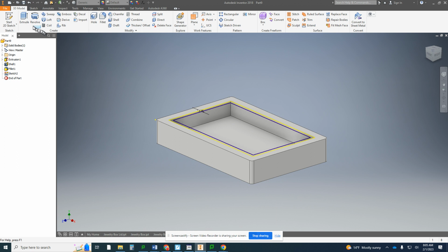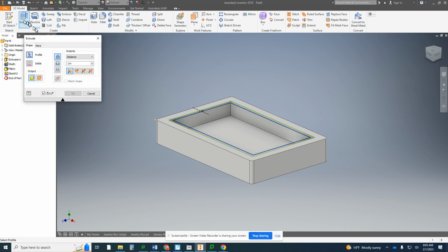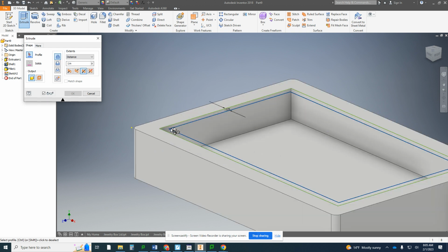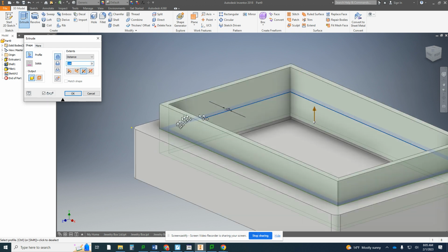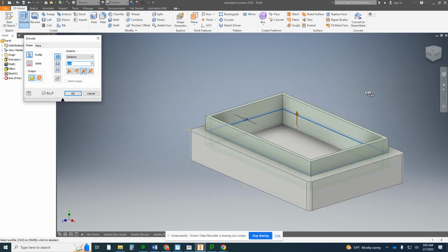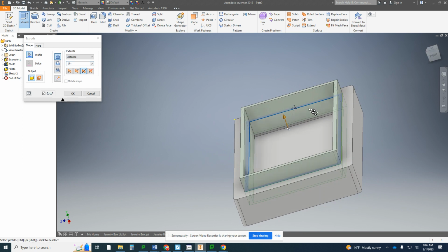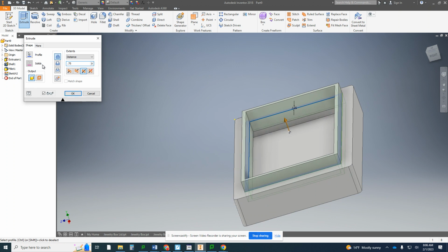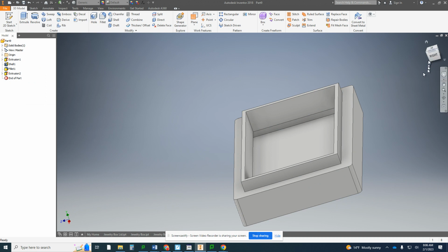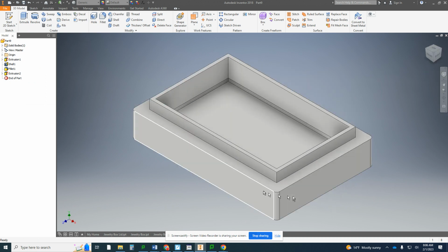Now what we can do is extrude this in 2 different directions at the same time. You'll notice this icon right here shows the plane being pulled to the back and the front. I'm going to click that, keep my 1 inch value, and click right in this section. And you see that I now have that rim going all the way around. And I made a mistake. We're going to be making this 3/4 of an inch, so 0.75. There we go. And now the build is finished.